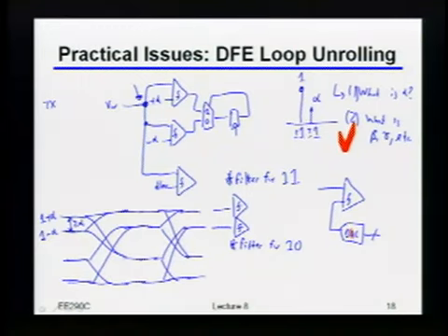So unfortunately, the only way you could do it is if you actually put an analog low-pass filter in the voltage domain in front of that DAC that was not interacting with the signal. And then you could do some filtering or something like that, but again, remember, when I do that (A plus B) over 2, there's nothing really driving me to the correct center point, right? Because all I know is the digital code associated with this level and the digital code associated with that level. That's not to say that the digital code associated with what's in between is even on average the right value. You see what I'm saying?